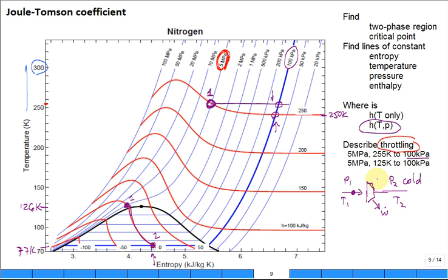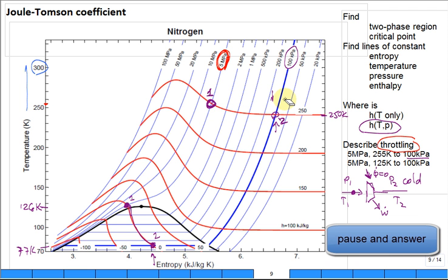Do you think I'm going to have any Q dot into it? Turbo expander? No, it's probably going to run adiabatically. No heat transfer. Shaft power out. Changing kinetic and potential energy, negligible. So what about the second law analysis? Where would I find the good state 2 if I ran it through that turbo expander? Oh, it's still going to that thick blue line of 100 kPa. Instead of state 2 being right here, where is state 2 possibly going to be?